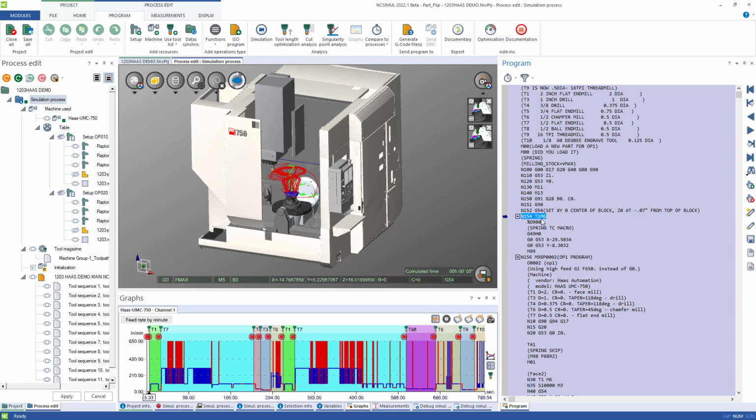In this case, when the tool changes happen, this is the tool change macro that's coming directly off your real machine. That way, you can get a really good and accurate cycle time estimation, as well as making sure that you're not going to get any unforeseen collisions when you're exiting the part. If you move Z, then XY versus XYZ at the same time, you'll know exactly how that's going to look ahead of time inside NC Simul.